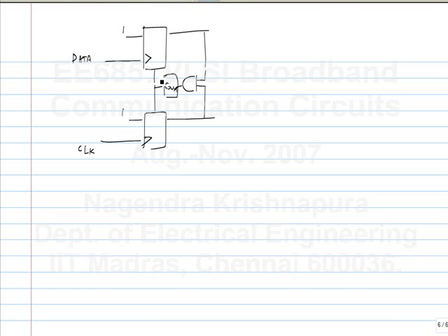Philosophically, you can't say. If you have all ones, what is the period of data? It can be data at 1 gigabit per second, 2 gigabits per second, anything. If it's all one, you just cannot say. It's only from the transitions that you can say data is of some period. And also, when there is no transition, there is no point in trying to detect the phase. It's only when there is a transition that you have to detect the phase.